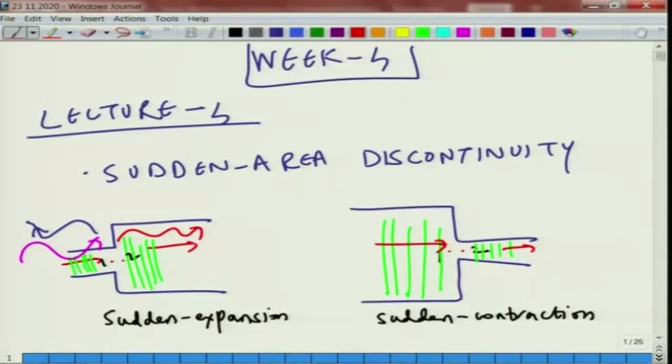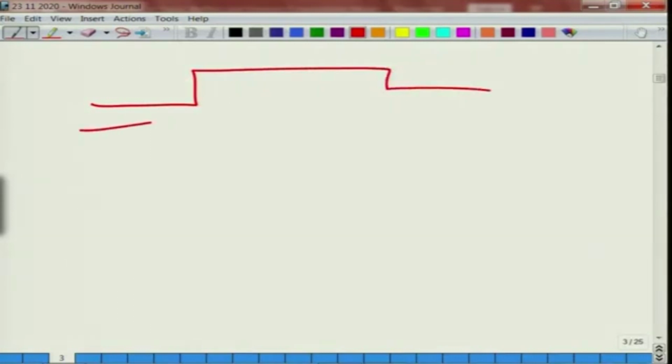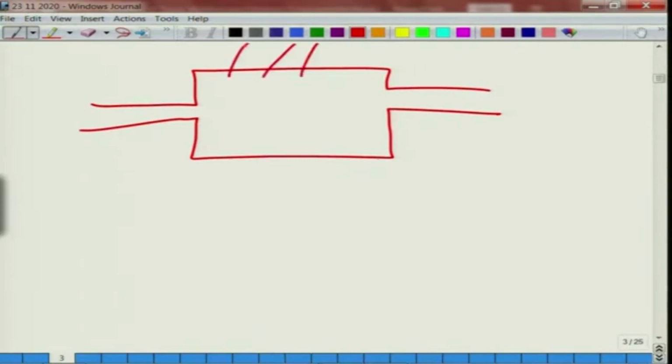So, how do we do the maths behind it, and why are these important, of course. If you consider a muffler that is basically a simple expansion chamber muffler, it is called simple expansion because there is a sudden area expansion and sudden area contraction, and it is called simple really because it is nothing but an empty chamber with no lining, nothing, a rigid wall chamber, so that breakout noise, the noise that goes in this direction, is not allowed.